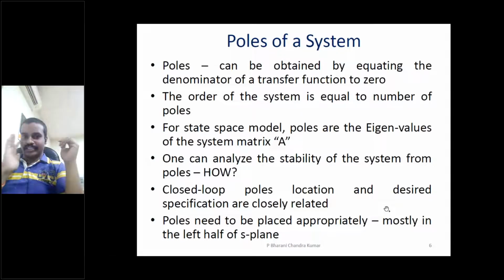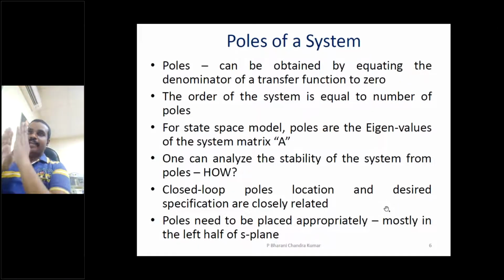That means it will not affect your system. The pole which is dominating your system is the one at -1, because that means very near to the imaginary axis, and hence it will slow down your system. So that's why we call the pole which is very near to the origin the dominant pole. And as I told, there is always a threat that if there is some variation in the plant parameters, that one dominant pole can go to the right half of the s-plane as well.